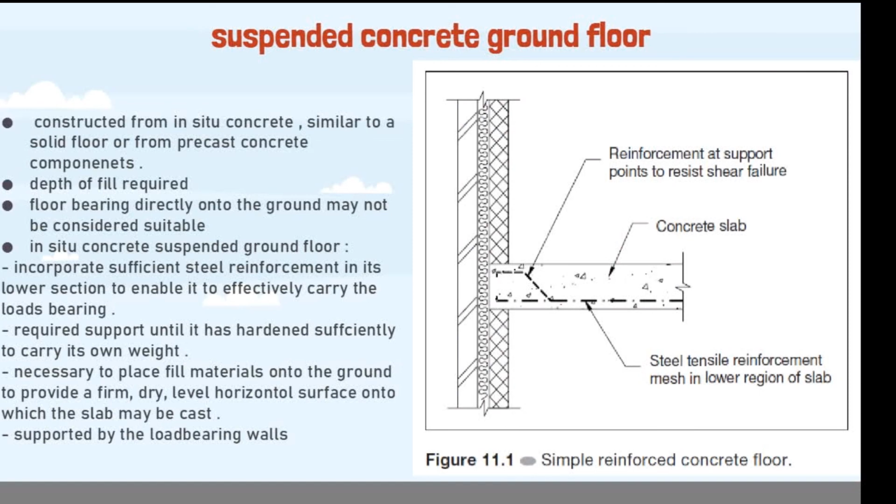In situ concrete suspended ground floor incorporates sufficient steel reinforcement in its lower section to enable it to efficiently carry the loads bearing and required support until it has hardened sufficiently to carry its own weight. It is necessary to place fill materials onto the ground to provide a firm, dry, level horizontal surface onto which the slab may be cast, and the last one, supported by the load-bearing walls.